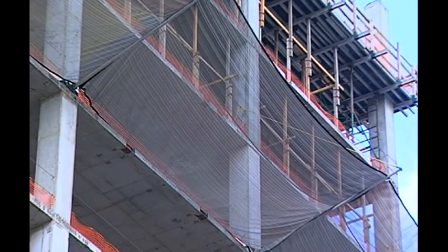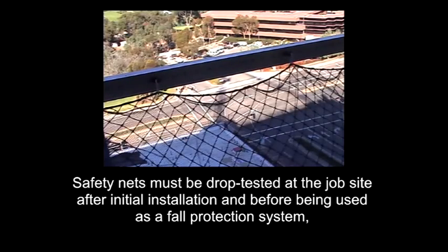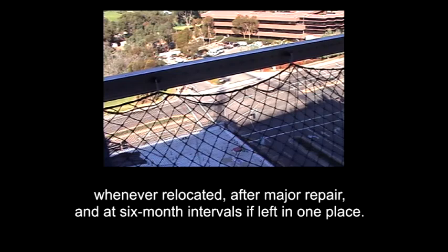Another option, safety net systems, should be installed as close as practicable under the walking working surface and never more than 30 feet below such levels. Maximum size of each net mesh opening must not be longer than 6 inches on any side. Nets must have a border rope or webbing with a minimum breaking strength of 5,000 pounds. Safety nets must be drop tested at the job site after initial installation and before being used as a fall protection system, whenever relocated, after major repair, and at 6-month intervals if left in one place.